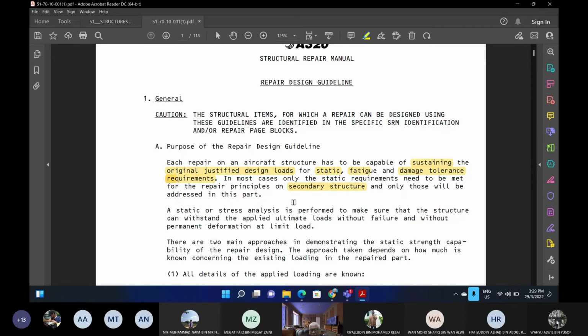First, you have to identify what is a critical crack growth, and then you have to look for the stresses on the area, and then you have to look at how the aircraft flies using the flight spectrum, and then from there you will be able to crunch the numbers to determine the inspection interval of the aircraft structure.